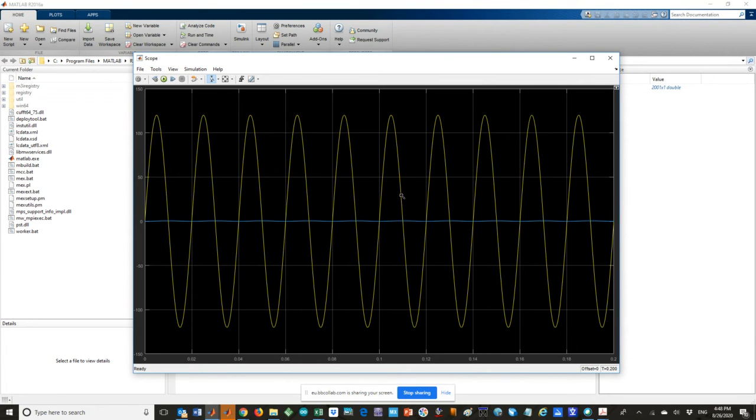This can be done for any frequency. If you have a 1 kilohertz signal, you have to take that into consideration. So 1 over 1 kilohertz will give me the time for one cycle to be displayed in that window. And now it depends on how many cycles you need to display. You multiply that time by the number of sequences, and you replace that one in time simulation, and you get that number of sequences.